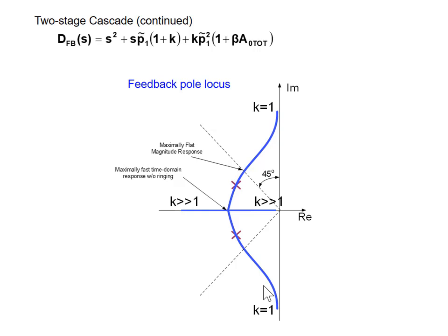Yes. Do we want to keep the poles in the same location so that when we go to the Bode plot, we get 40 dB per decade at one point instead of like a 20 and then 40 later? What's bad with 20 and 40 later? The designer might want it all to happen right at the same time. Why? I don't know. It'll work great if you make the separation even larger so they're out here. But what's going to happen is your closed loop bandwidth is going to be lousy. You're going to spend a lot of power, and you're not going to get much frequency response out of it.